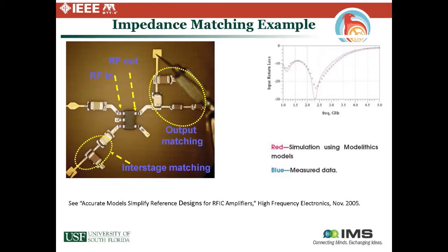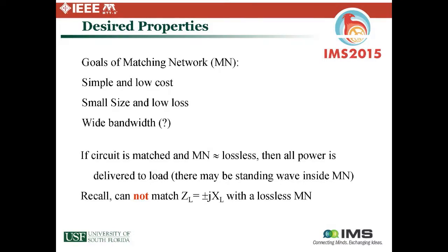What about bandwidth? Well, a wide band design is going to be a lot more challenging to achieve a match. There's going to be a trade-off in the quality of the match versus the bandwidth and the complexity of the network that you need. Our purpose today is to keep it simple, and we're going to be talking about narrow band designs. I have a couple references at the end for broader band matching, and there are a lot of synthesis tools out there, including built into ADS and other simulators.